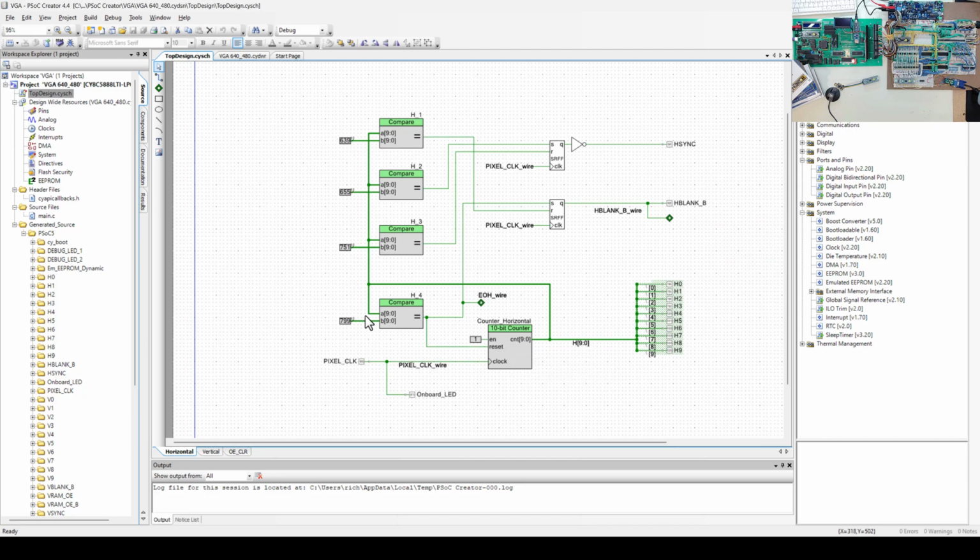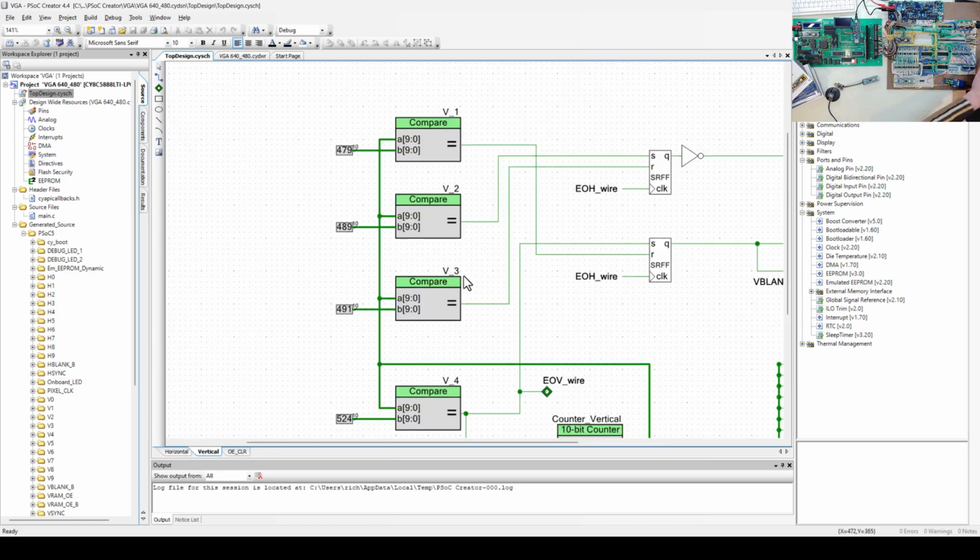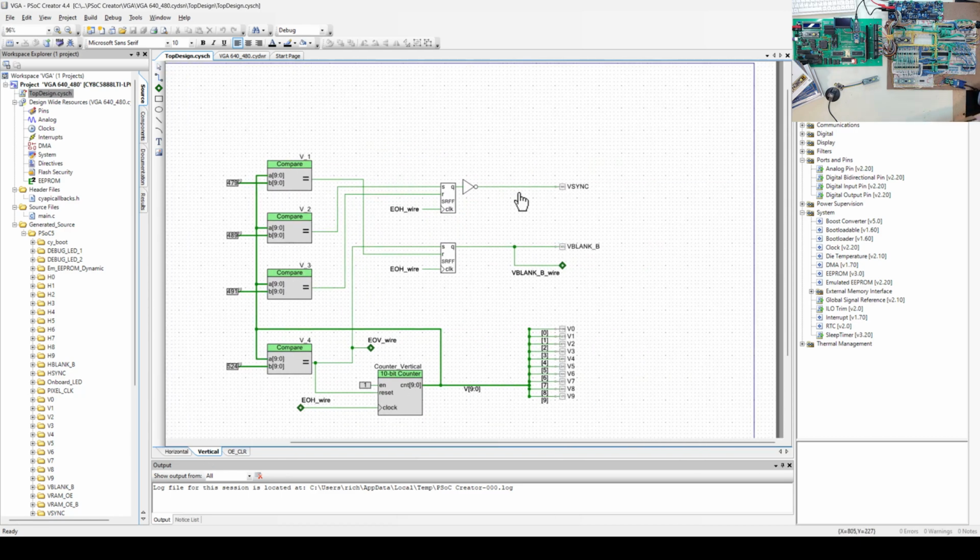And if I hit those certain values, then I maybe flip something and say, okay, that was H-sync or that was H-blank in the timing of how I'm drawing my video screen. And here's part of the addressing, so that as it's rotating through all those numbers, I know which color data to pull from, whether it's a ROM or, in my case, my video memory, the RAM. So that's the horizontal. Then I do the same thing. I've got something similar for my vertical to generate VSync. And those VSync addresses, or vertical addresses, all the horizontal addresses plus vertical addresses, is what I use to access addresses in my static RAM for my video card.